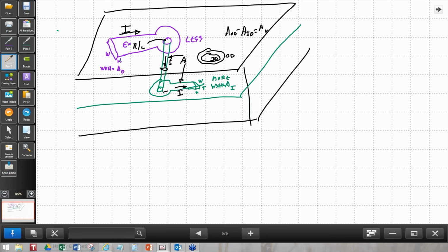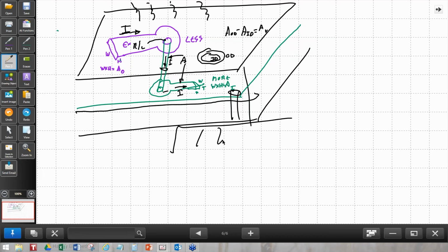Overall, you're going to have to decide, how does the heat get off the board? Just pushing it on from one layer to another doesn't get it off the board. Does it have to just come up off the top surface, or does it have to actually conduct to a plane layer that has a mounting hole, and the mounting hole is bolted to some kind of a chassis? You need to decide your thermal paths. So you can't actually get an absolute answer to that unless you know exactly where the heat is going.